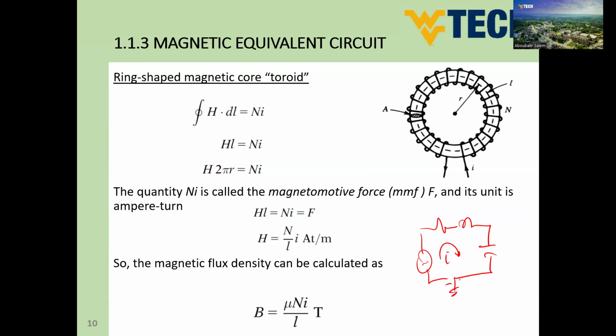I know all of you will say we can apply Kirchhoff's voltage law here. So I is going to be V divided by the total impedance of this circuit, so R plus jXL minus jXC. This is the relation that we can describe here.